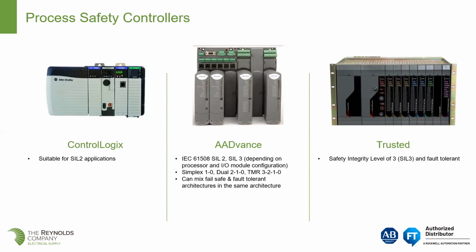We can do that in the ControlLogix platform up to SIL 2, and then we also have the advanced and trusted products that can get us up to SIL 3. So if you have some process safety applications, definitely talk to us, and we can help determine the right platform for your application.